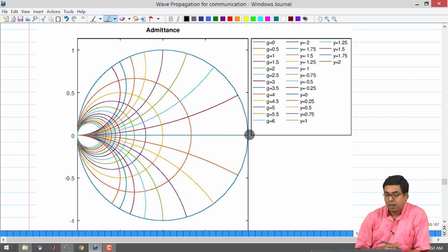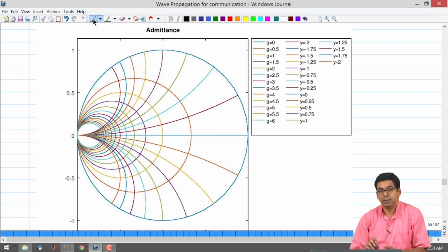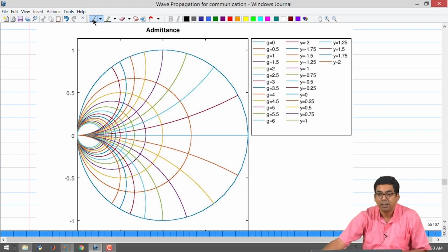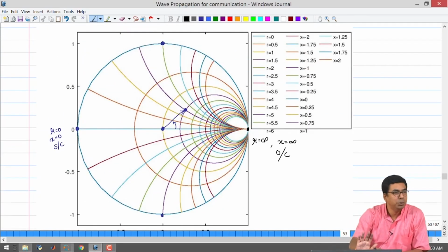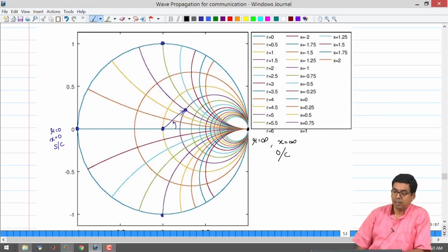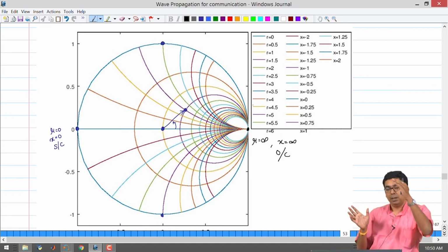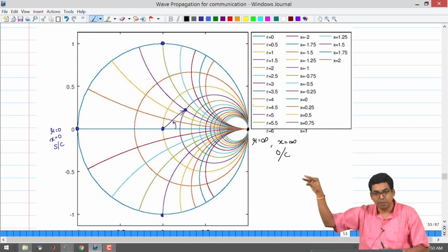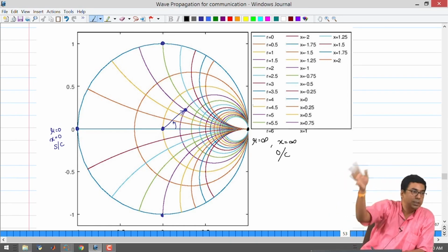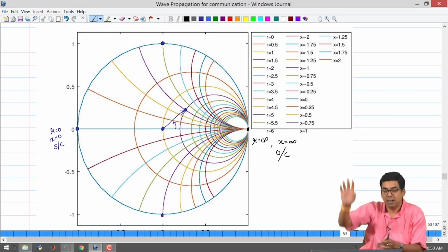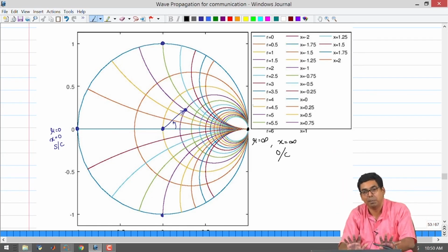Okay. But I have never seen somebody use admittance Smith chart like this. Usually when people talk about Smith chart, they usually have a way of orienting the Smith chart before starting any problems. They always do the orientation in this manner, right. That is, as you go to the right, the circles should become smaller and more closely spaced, all right, and your reactance, constant reactance circle should go from the right side branching out. So, it should be flaring out from the right hand side. This is the normal orientation of Smith chart that people use.